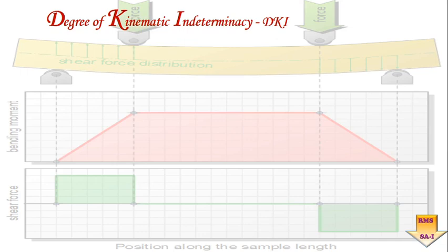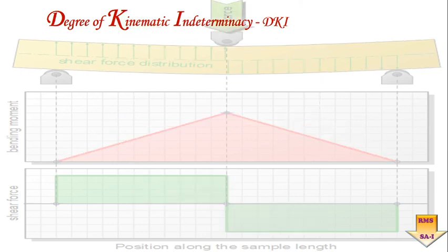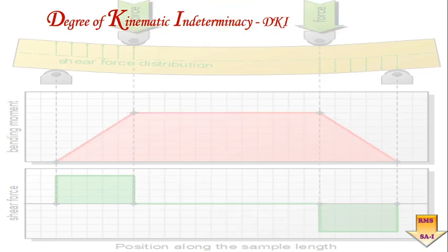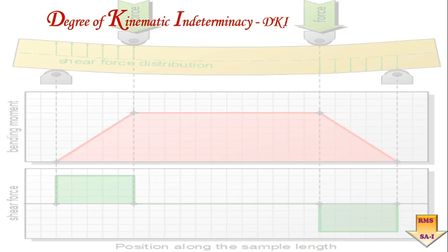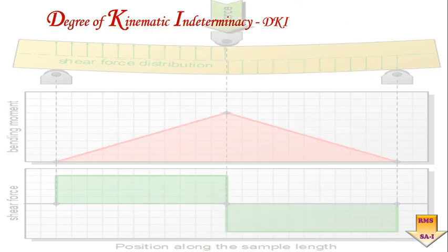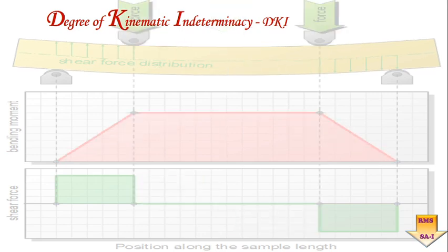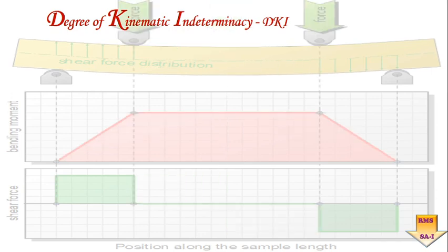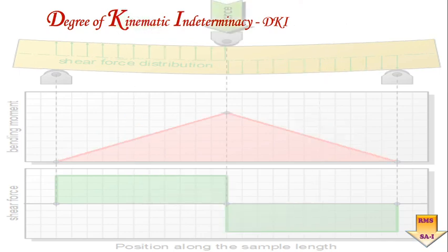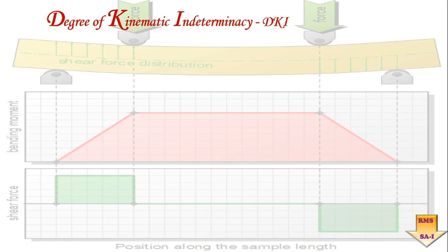Here, as we are dealing with displacements, in order to have a displacement there has to be certain motion. So about a particular joint, whatever motion takes place, horizontal, vertical, or clockwise or anti-clockwise, those are nothing but the displacements occurring at that particular joint. So this terminology, the degree of kinematic indeterminacy, is very important to understand before understanding the displacement method or any methodology related to it. So let us understand what this degree of kinematic indeterminacy is.